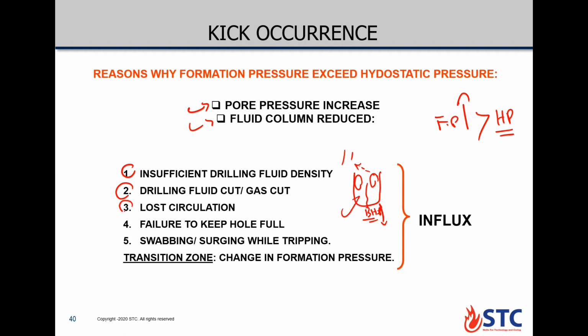Number three is lost circulation. Lost circulation means you lose some mud inside the wellbore or inside the formation pore space. So guys, does every lost circulation situation lead to influx? Can anyone share? Does all lost circulation lead to an influx? No, because if we get losses in one formation, we cannot get influx from the same formation. We have to get influx from another formation, I think.